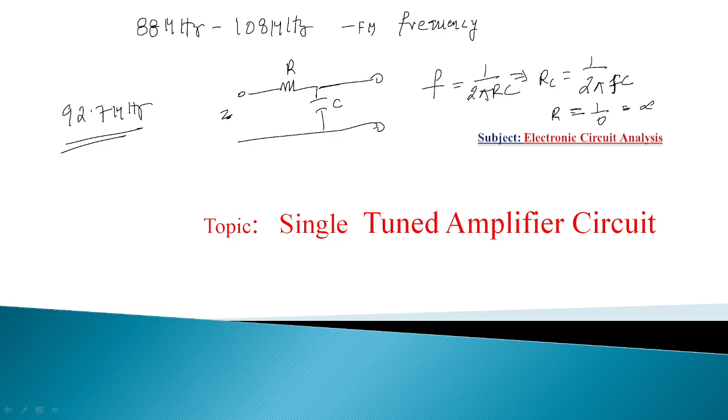So we get infinite impedance while applying a zero frequency signal. Means the reactance across the capacitance is infinite, so whatever you are giving will be available across the output here. Low frequency signals are available.